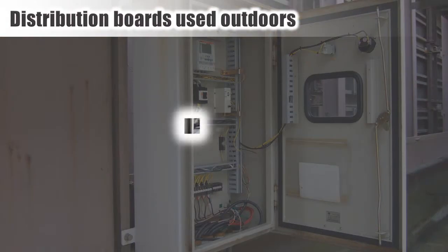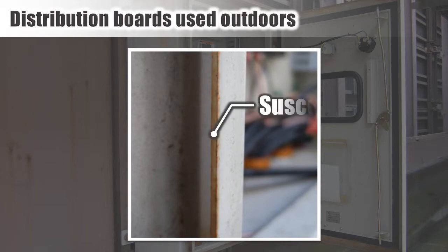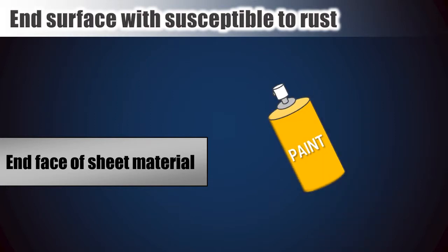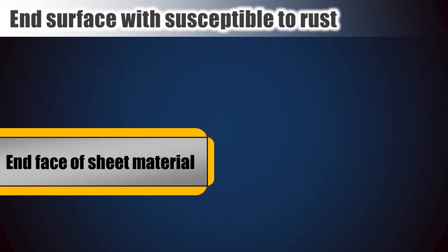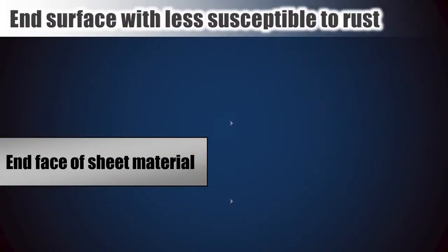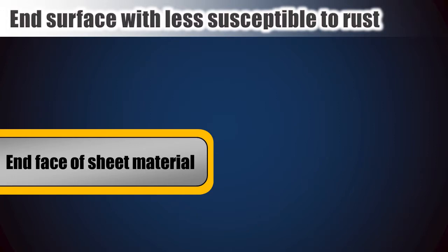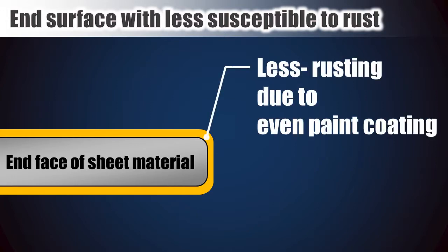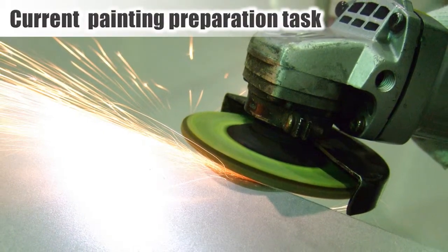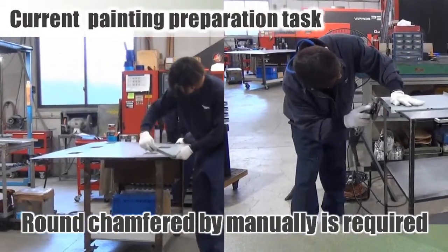One of the spots that are susceptible to rust is the end face of sheet material. It depends on how it is painted, but if the edge of the end face is sharp, the coating paint is thin and is more susceptible to rust. By finishing the sharp edge of end face into radius, the thickness of paint on edge is more even, therefore less susceptible to rust. So the sharp edges are round chamfered by hand before the painting process.